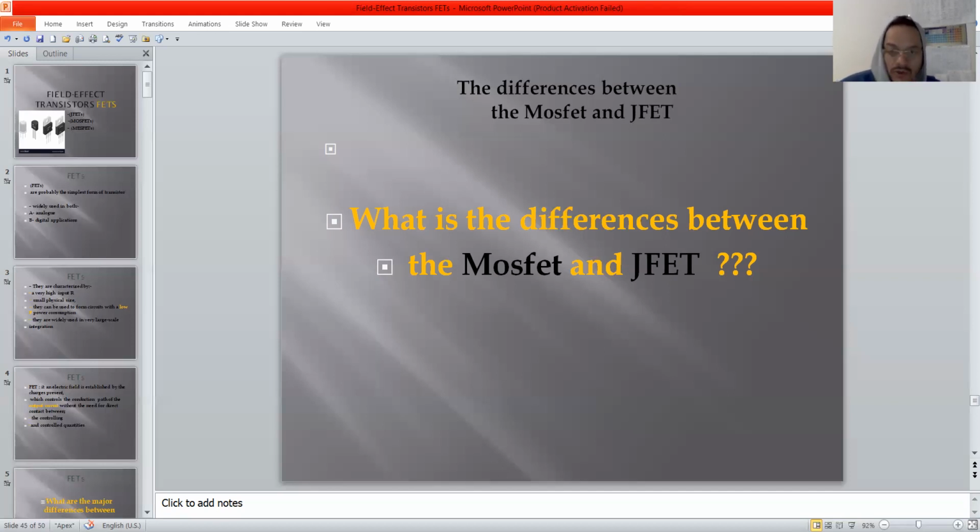Let's take a look at these important notes. Here, increasing resistance narrows the channel. That means when the resistance increases, the channel will be smaller. And the channel resistance, like I said before, will be constant as the drain source voltage increases and approaches a level VP. What does VP mean? VP is the pinch off voltage.